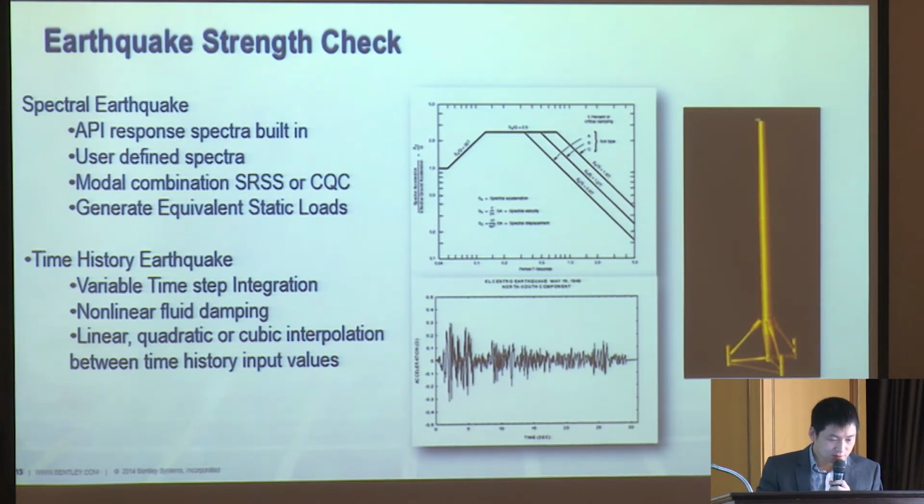Then we input this time history data in SACS and we can do a time history simulation and get the dynamic response of the structure due to earthquake.